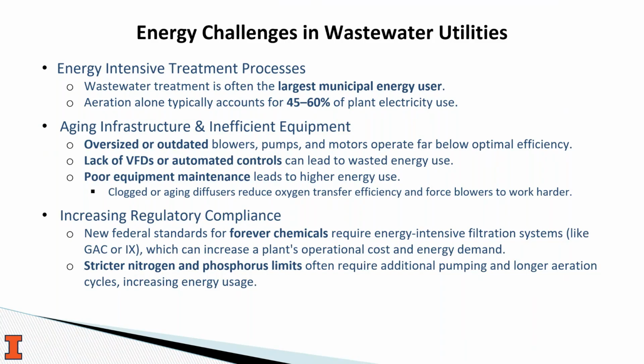Another challenge is increasing regulatory pressure. New federal standards for contaminants like PFAS and microplastics often require a little bit more energy in filtration systems, or just additional equipment or treatment processes to be added, and stricter nitrogen and phosphorus limits can require longer process times, or longer aeration cycles and more pumping.